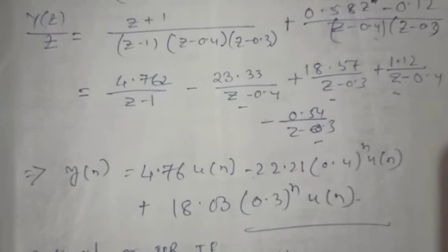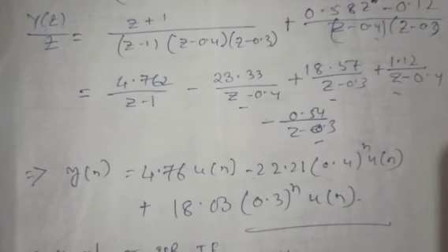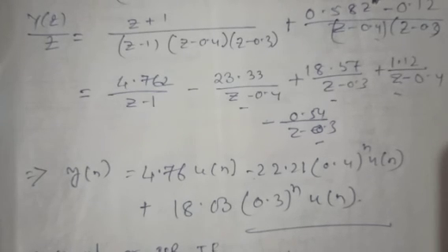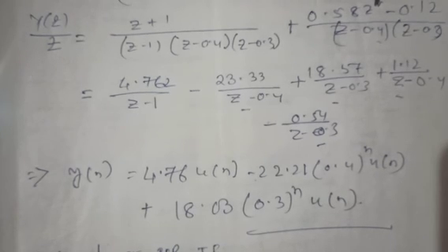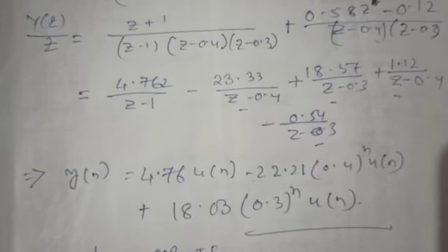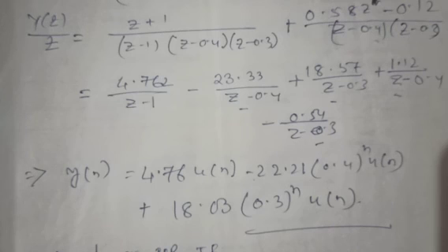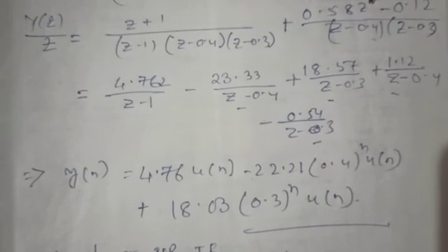Okay, so time domain response, zero state response, zero input response, from which we got the forced response and the natural response. So similarly for the forced response, we got the homogeneous solution and the particular solution, and finally combining both we will get the total solution of the systems. The same solution can be done using the Z transform. For that you need to take the Z transform of the equation, then put the given conditions, and finally take the inverse Z transform. Okay, so this is all about the time response analysis of this.